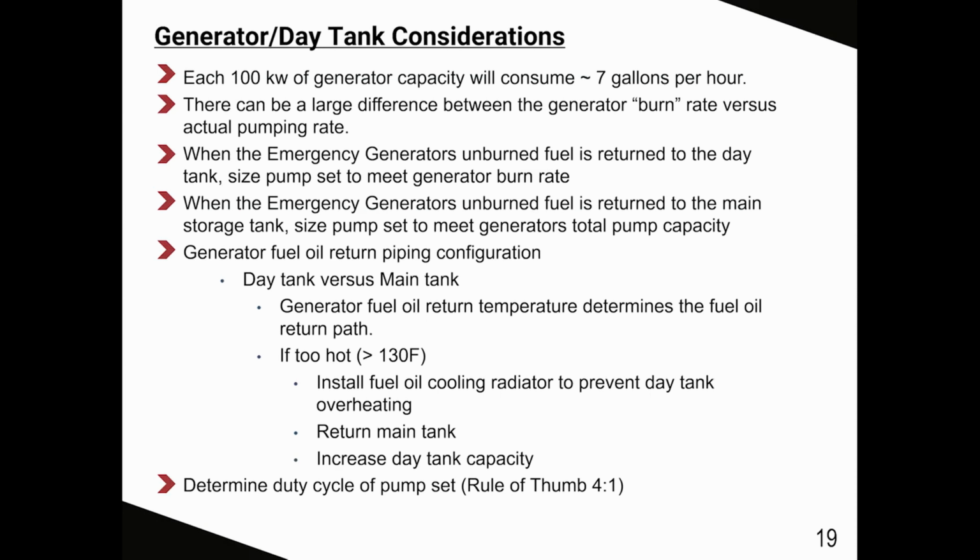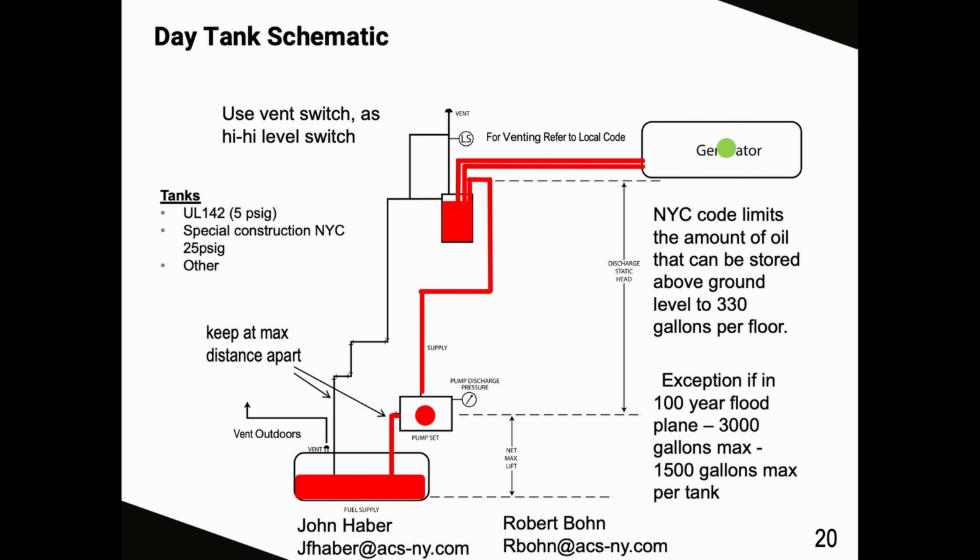So John, how long has that 7 gallon an hour per 100 kW rule been around? The 7-gallon rule per 100 kW has been around since I started in the mid-90s, so it's been around a lot longer. It's a representation of a typical New York City generator installation.